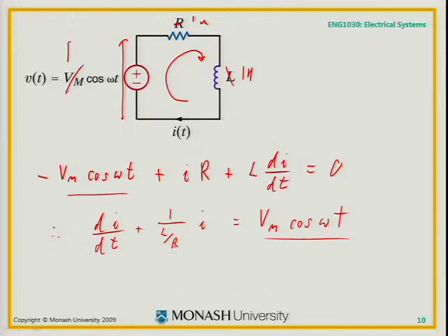You can see down here the time constant of the transient is L on R, same as we got last time, but we're in fact not so much interested in transient behaviour now. It's what happens when that's died away. What are we left with? Now take the special case where Vm equals 1 and L and R are both 1, just to make it as simple as we can.